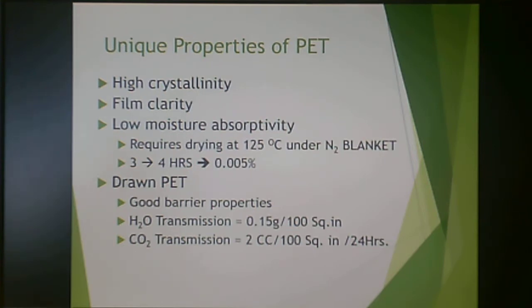Moisture in the presence of a resin can often act as a plasticizer, and so if you don't remove moisture in resins that can take moisture up, you get poorer mechanical properties or poorer aesthetic appearance. So if something needs to be dried, it should be dried.